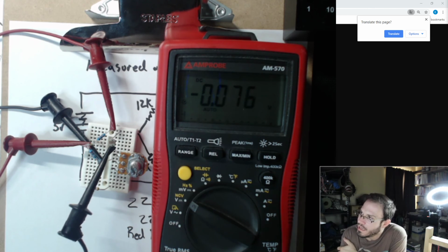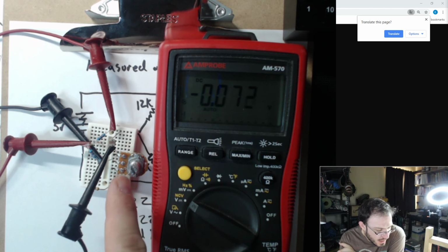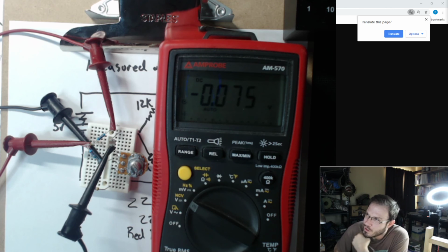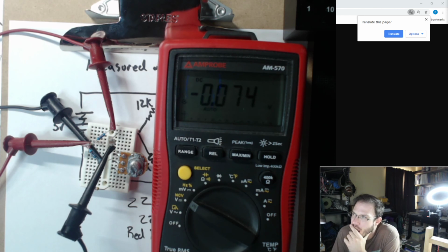Though if you wanted to very accurately measure resistance, a Wheatstone bridge can do it better than your multimeter if you set it up right. But you can use it as a very fundamental good starting point for creating a sensor circuit. Okay? So that's where the Wheatstone bridge is going to shine these days, is for constructing sensor applications.